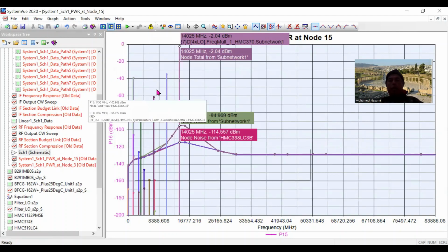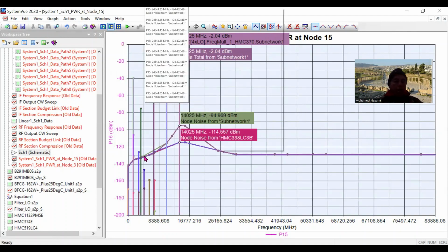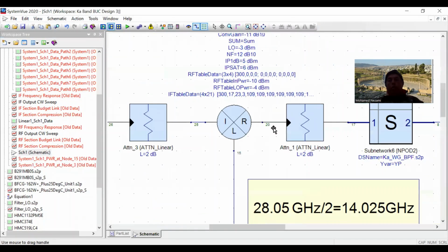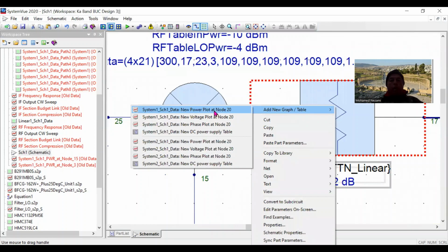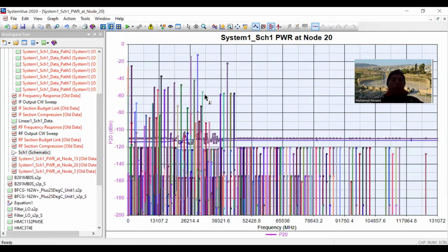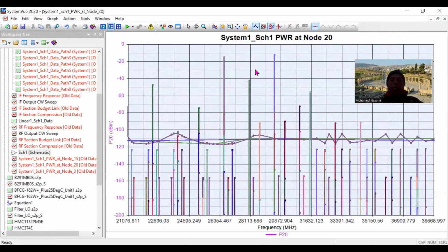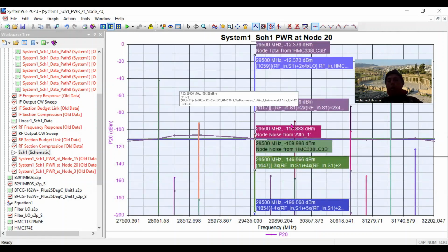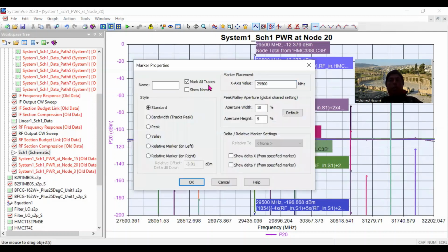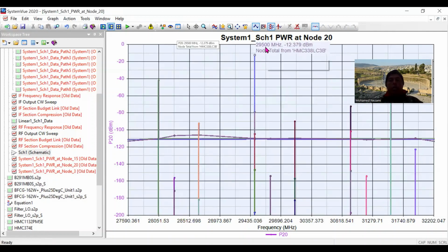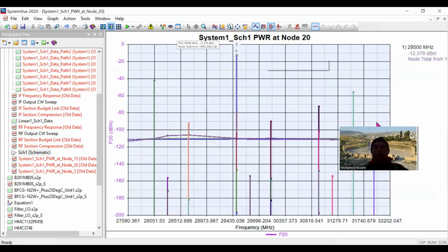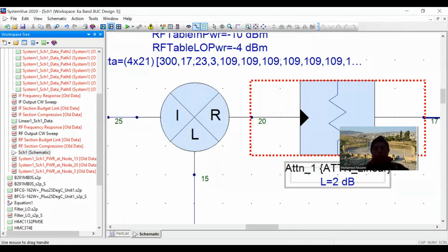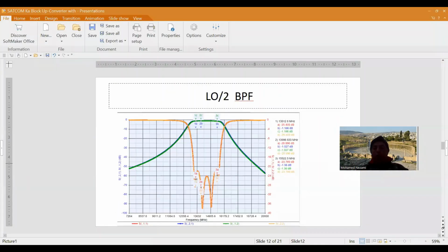Okay, now these harmonics are okay, they can go in and they interact and so on. And of course what we end up with, if you look at the IF signal in here, is this big spectrum, and of course all the subharmonic products, but we end up with one here, which is basically where the desired signal is, at 29.5 gigahertz. Okay, and we can just ignore this stuff, and that's this value here. Okay, and the nearest ones are rejected way down. The lower sideband is not rejected yet, so it's going to be rejected further in the bandpass filter. So we go through that. That's the harmonic LO filter.